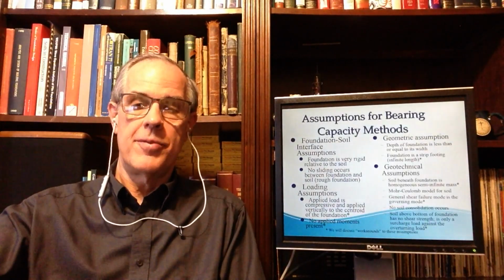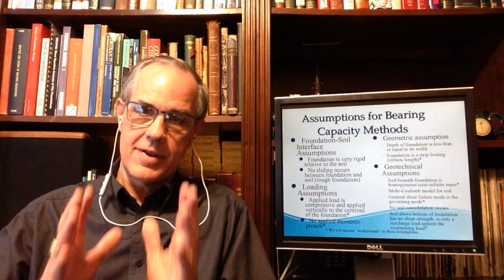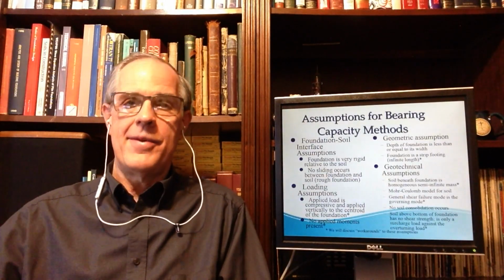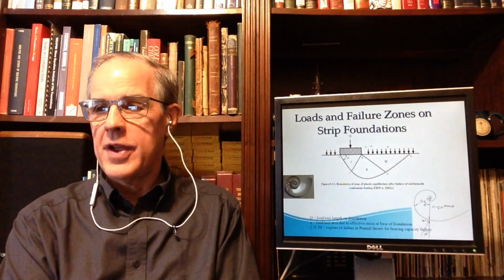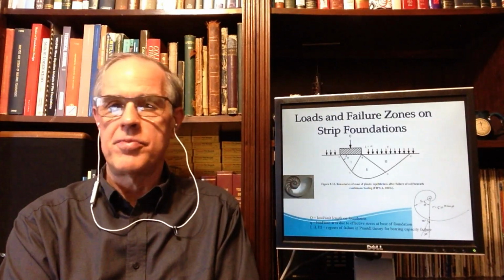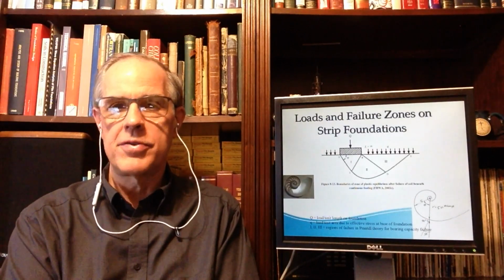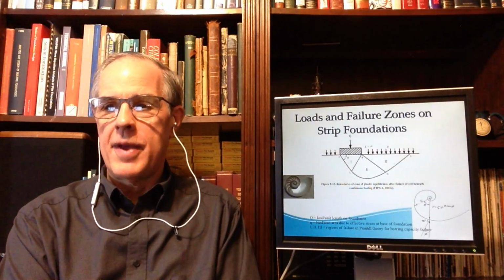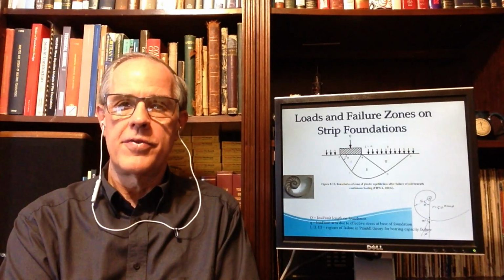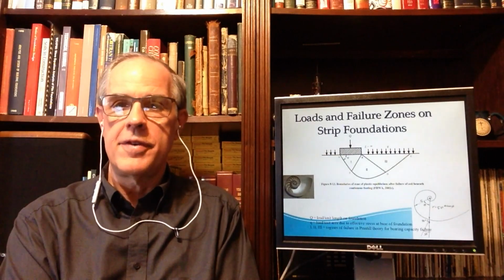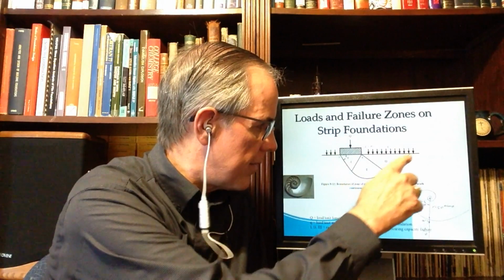Those are the basic assumptions, and this is a typical way that a geotech method is developed. We develop the basic theory, and then we start playing with it. Load failures are basically assumed to be in a log spiral, like the nautilus. And basically there are three failure zones, as I talked about earlier, for the general bearing capacity failure. The surface is along here. Nice failure surface.